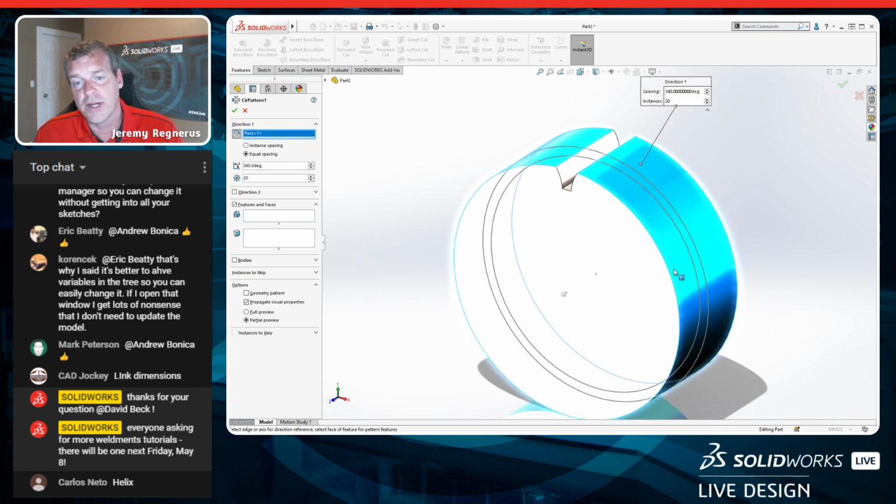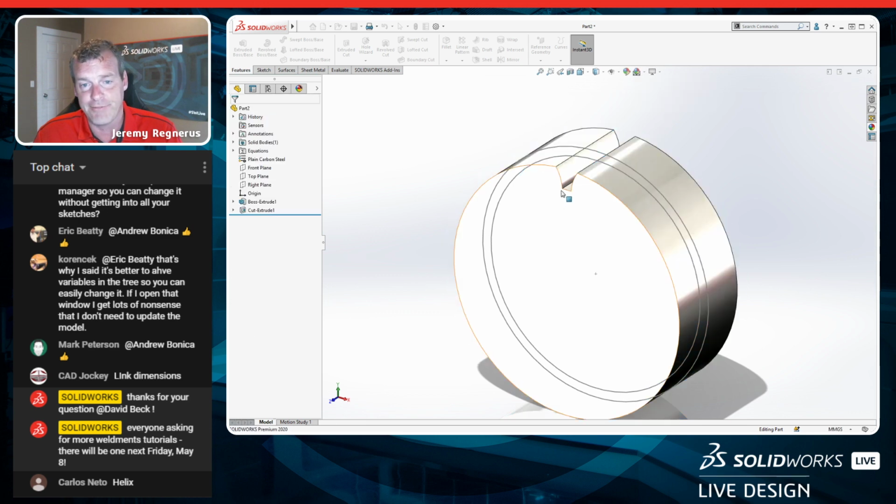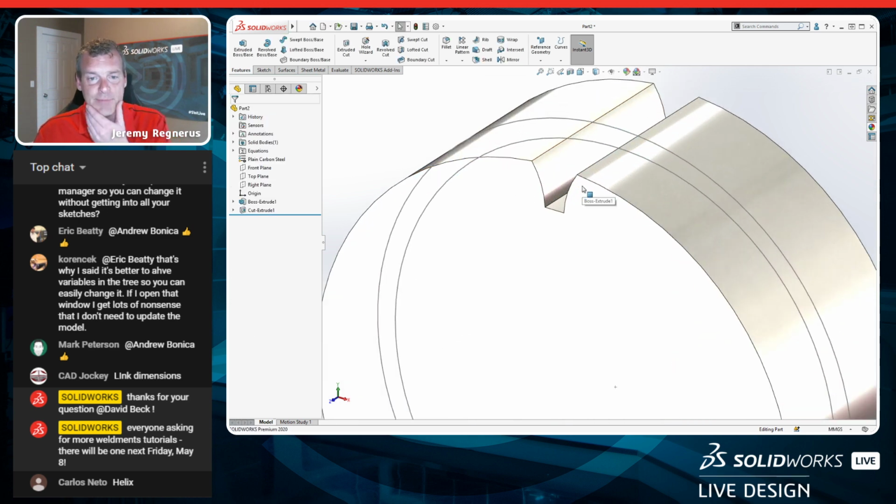But we're going to go ahead, we're going to create the circular pattern about this face. The features, oh, we need to add a fillet in the bottom of this tooth. I forgot about that. My bad. This fillet could be created in the sketch, and there's no reason not to do this. But we actually want to create the fillet here because one of the questions asked earlier on was, how can we use equations in features as well? So we're going to take a look at this.